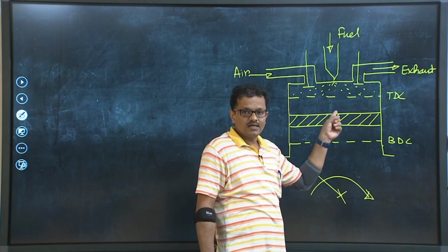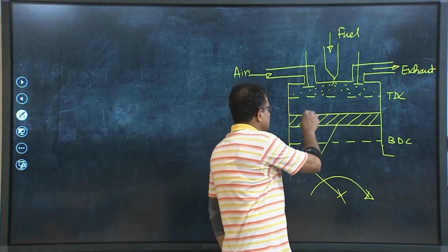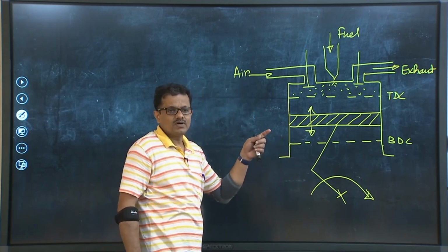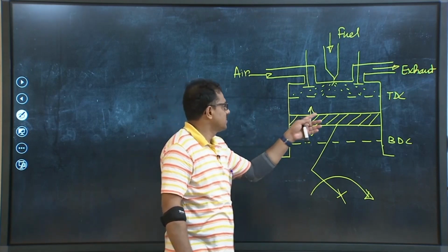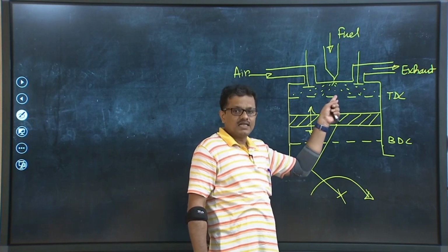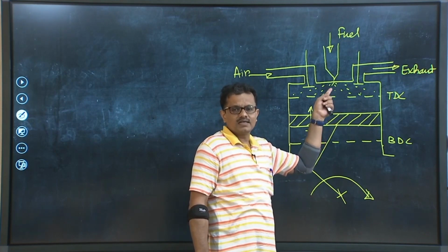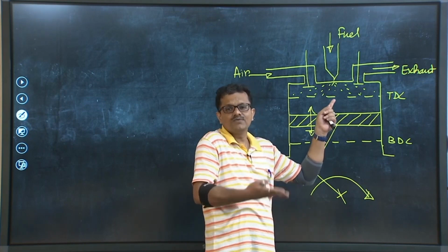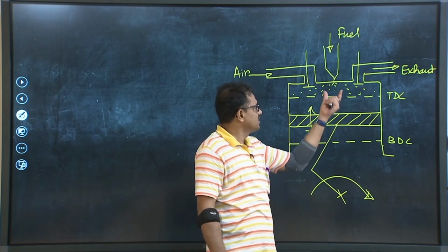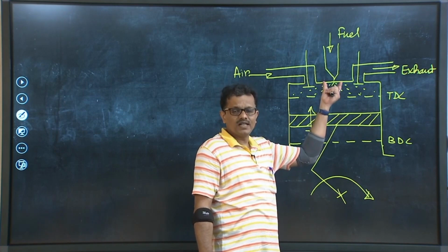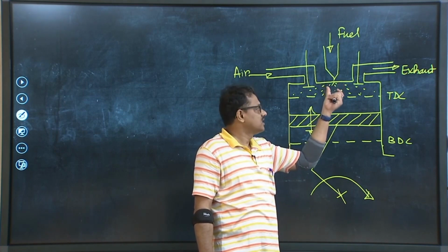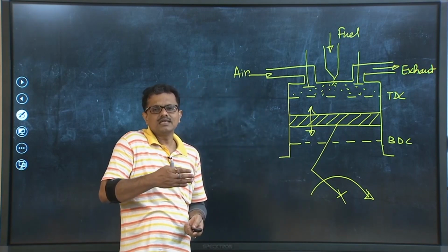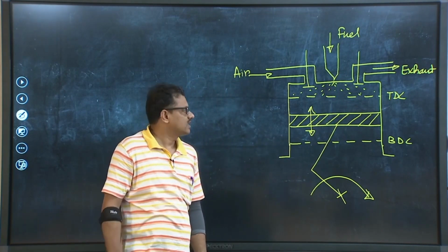As I said, the movement of the piston is very spontaneous, and it is very difficult to assume that the piston will be at TDC and the entire combustion will be completed during that time. This is not possible, accounting for the ignition delay, because supplying the total amount of fuel needed per cycle requires a certain amount of time.